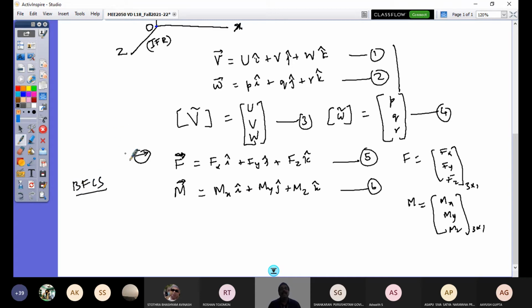So at the CG location of my aircraft, these force components, and with respect to the axis at the CG location, these moment equations are going to govern my vehicle motion in space. So how are they obtained? That's coming from our basic fundamental understanding of momentum. To get your force, differentiate your linear momentum with respect to time. To get your moment, you differentiate your angular momentum with respect to time. So we are going to take those basic dynamic fundamentals and derive this now.